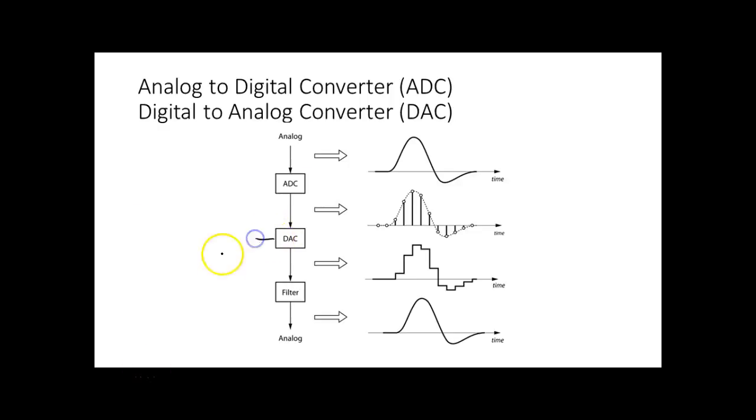Yeah. And when I put a binary number on that DAC, if it's a 10-bit DAC, then it's going to give us 1023 steps. But the analog output is going to move in what? It's going to move in steps. So if I was to see a sine wave, the sine wave looks like that. But I think I showed you on our digital scope over there, and it was actually in steps. And this is straight up. I'm doing it at an angle.